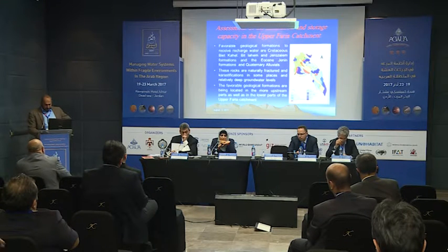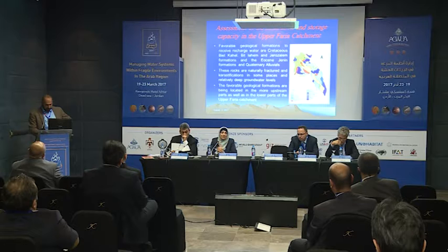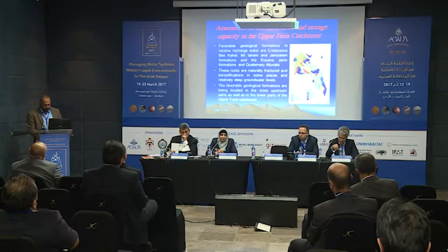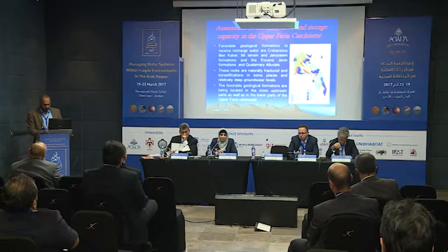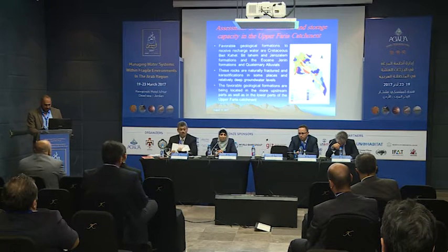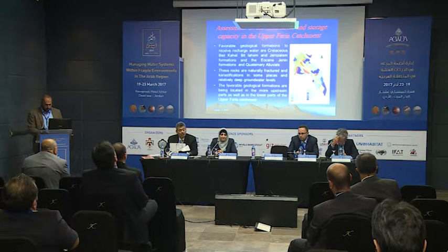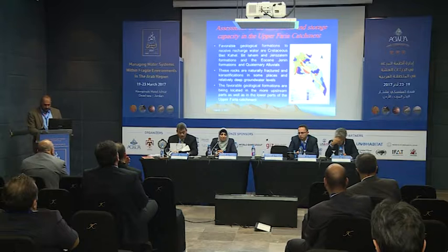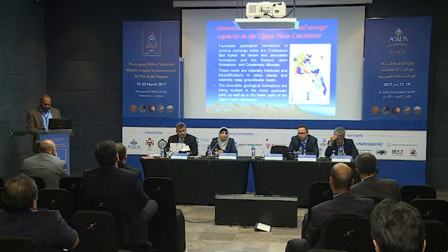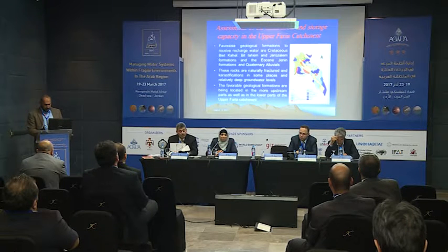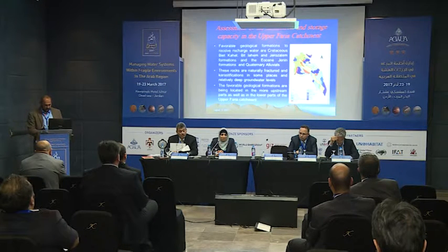After deciding the location of the dam, we make an assessment of the infiltration and storage capacity in the upper Faria catchment, or exactly at the location that will be used to construct the dam. In general, the favorable geological formations to receive recharge water are the Cretaceous Bet Kahel, Bet Lahem and Jerusalem formations, the Eocene Gene formation, and the Quaternary alluvial.